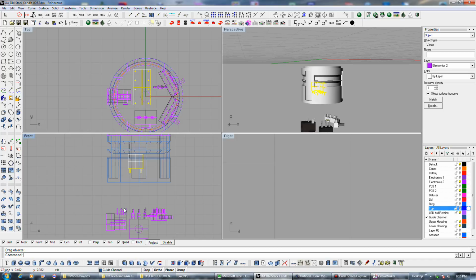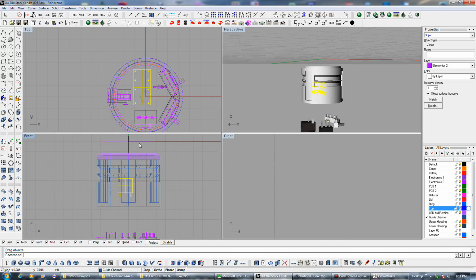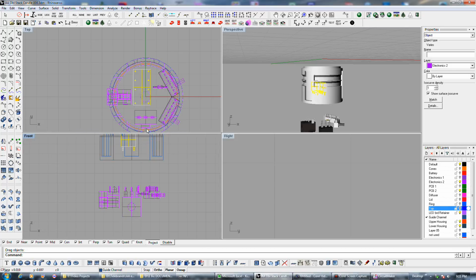I could take advantage of that and just have these wires come out here, and I solder them. These 4 lead wires come off this thing, and I solder them to the circuit board before I assemble these 2 halves, because I'm going to have to solder other wires coming from the LED board up above to this as well anyway.